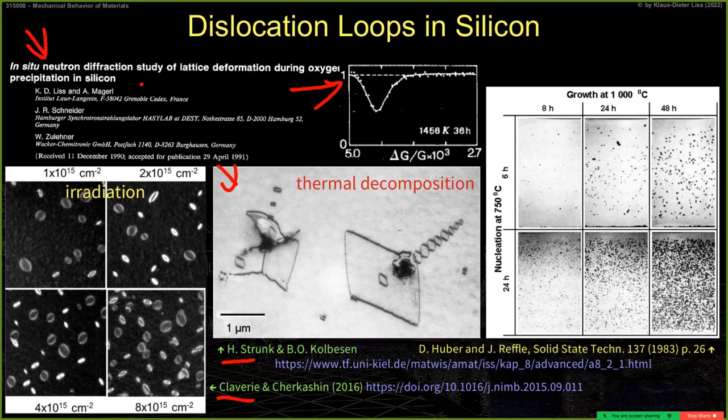I forgot the melting temperature, but at very high temperature, and then it's cooled down relatively fast, and you get oxygen dissolved, which comes from the crucible, inside the silicon. And then it's quenched to room temperature. So it takes a long time for the precipitation. It is quenched to room temperature, and you get a supersaturated solution of oxygen.